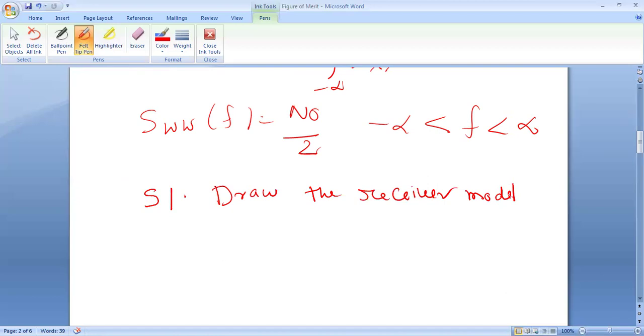We all know that the front end of the receiver is the RF amplifier, which is a wideband amplifier, followed by the IF amplifier, which is a narrowband amplifier. So whatever you are going to measure at the receiver output does not depend on the RF amplifier, but on the IF amplifier. What will the IF amplifier do? It is not going to pass all the signals received. It is going to restrict the signal up to a specific band, having center frequency at IF, and pass it to the demodulator. So the generalized diagram for the receiver model can be represented in this manner.